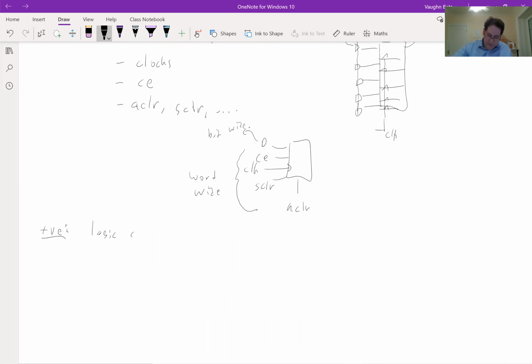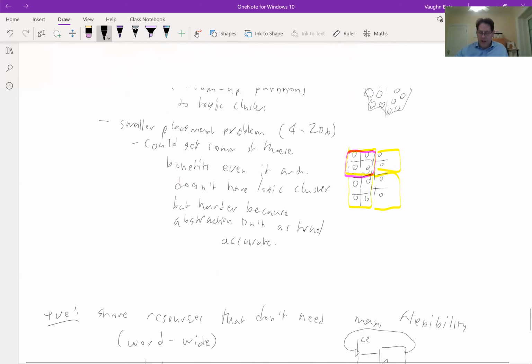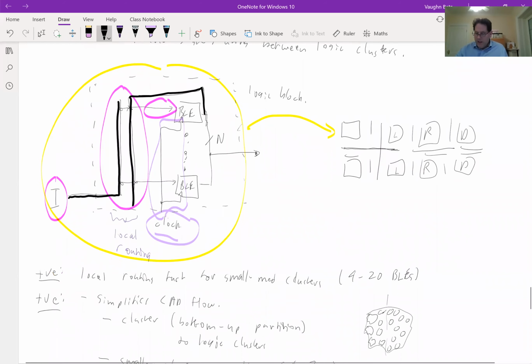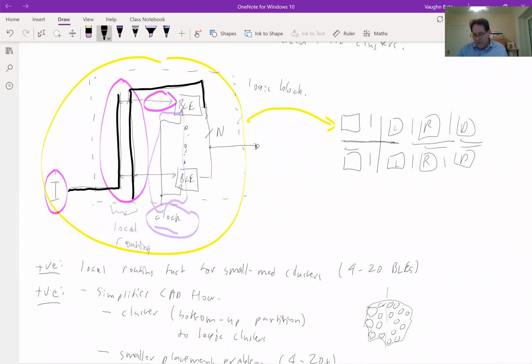And you have to lay all those things out, and they all have to line up nicely in a grid. So the programmable routing wires, the wires of this island style routing that I'm drawing here, kind of line up nicely as you go from logic blocks to maybe here I put in some RAM blocks. When I go from logic blocks to RAM blocks, the programmable routing has to keep going. And then maybe here I put in some DSP blocks. So we need to match these layouts where all the routing wires can go straight across these blocks.